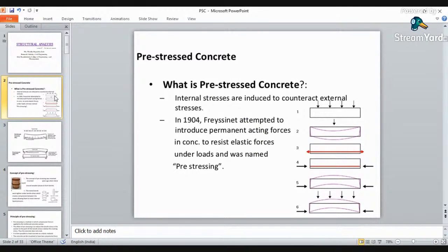When we are dealing with RCC, when we have to design our reinforced cement concrete structure, deflection is there. Too much deflection can be considered within the service line. Those cracks do not only look bad, but in an actual structure they could allow water and contamination to come into contact with the reinforcement. Eventually what will happen? This will corrode or weaken your reinforcement. So this is the drawback of your RCC.